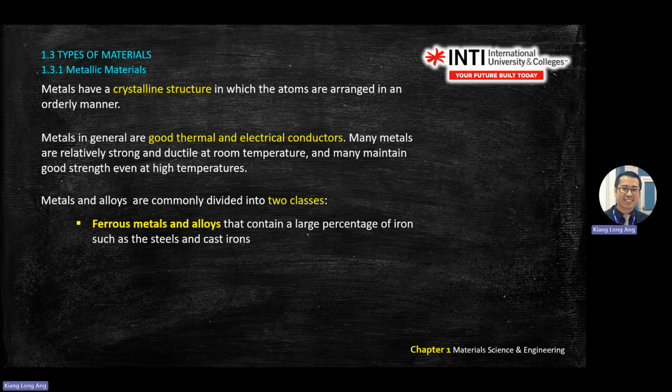You hold it with the red dot, then burn it at one end, so the heat comes from here. Once you put it here, you start the clock. Then when the nail drops, you measure the distance, the time and the length. Then there's an equation to calculate the thermal transfer. This is one of the lab experiments.